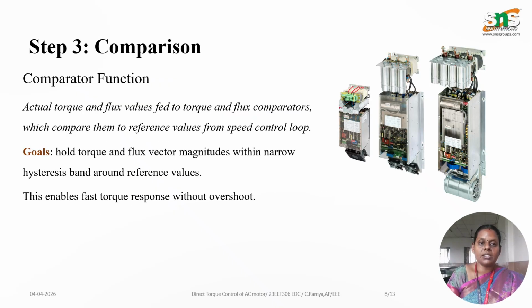Next, step 3 is the comparison. Here the actual torque and flux values are compared with the reference values. So the comparator maintains these values within a small hysteresis band. This also ensures a quick torque response without overshoot and improves the system stability.